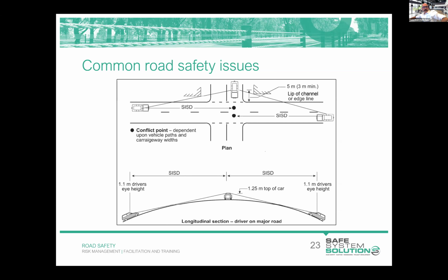Most people saying a safe intersection sight distance, although a few got tripped up there with standard intersection sight distance, but safe intersection sight distance it is. That's right. And it's unfortunately not standard intersection sight distance. It's a requirement that often is sort of compromised on.